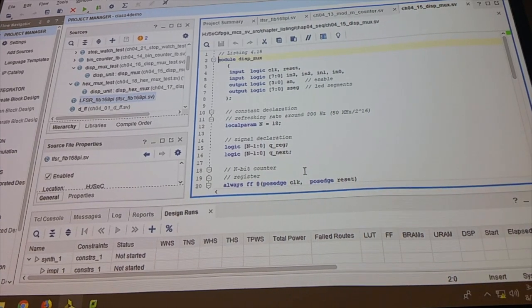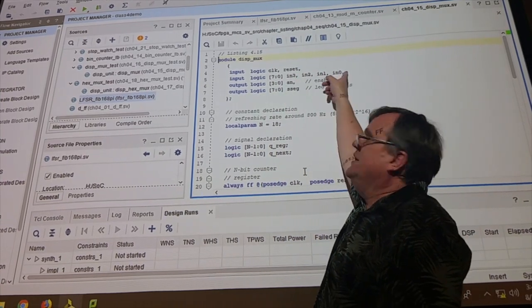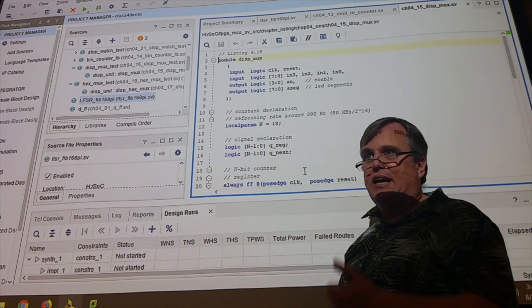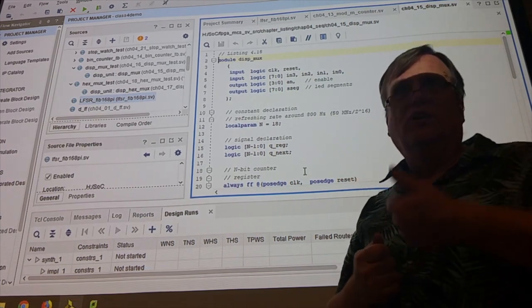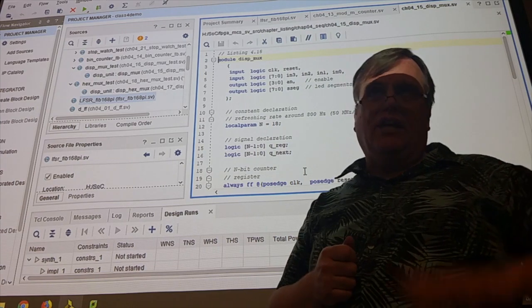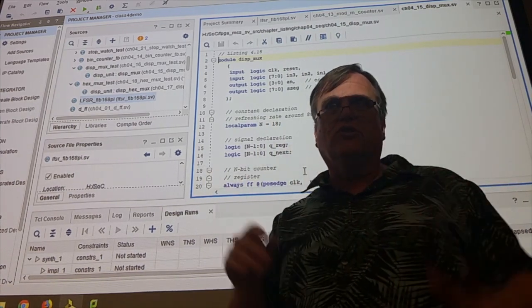And then in the master module, you would just instantiate this, hook those to the output, and this is from wherever you're generating the number from. So you would just have to make something that converts from your number to the 7-segment display. And they give you one of those as well. I believe it's actually in an earlier chapter, but you can look to see.